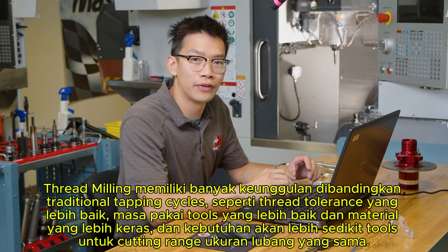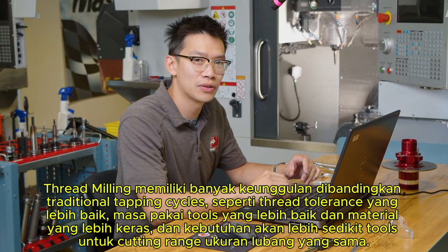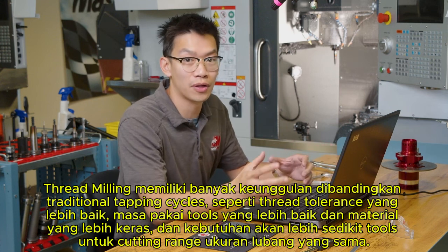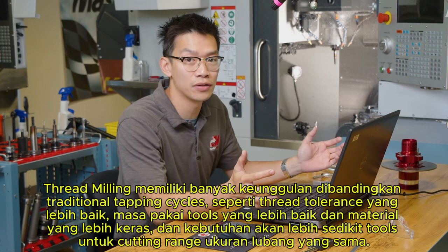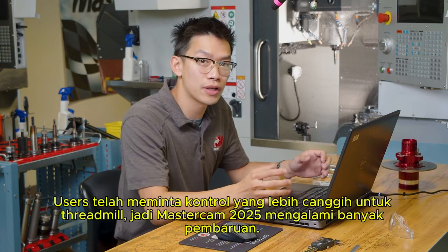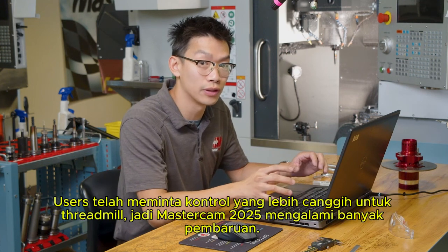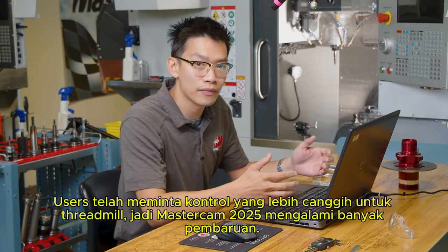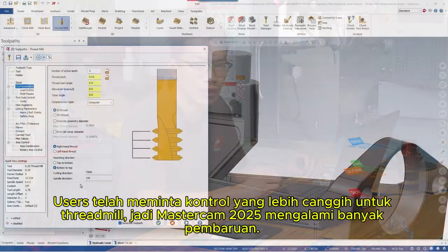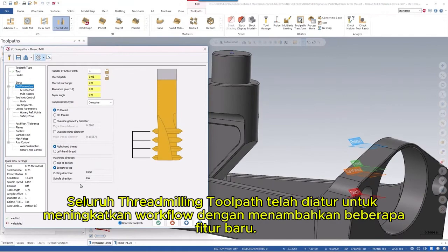Thread milling has a lot of advantages over traditional tapping cycles, such as better thread tolerances, better tool life in harder materials, and a need for fewer tools to cut the same range of hole sizes. Users have been asking for more advanced control over the lead moves for Threadmill, so starting in Mastercam 2025, it's received numerous updates. The entire thread milling toolpath has been gone through and organized to improve the workflow along with